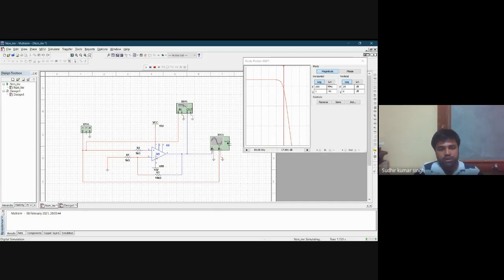what is happening. So what I have done is, I have just connected, at pin number 2, R1, and RF is connected between 2 and 6. So I have given a negative feedback, and then I am giving my input signal to pin number 3. So earlier in the non-inverting amplifier we had grounded it, and this input was given to pin number 2. So you can even check and see what is happening.